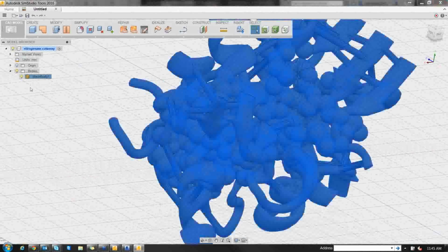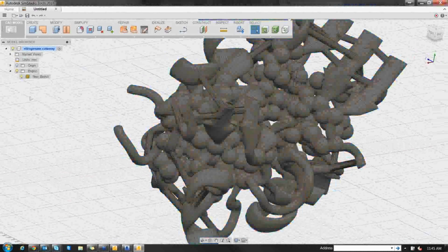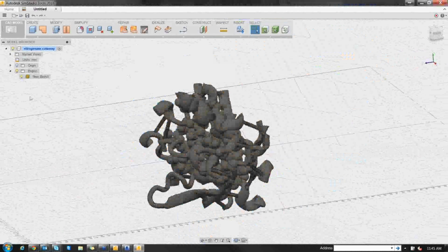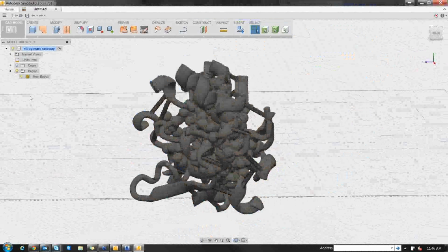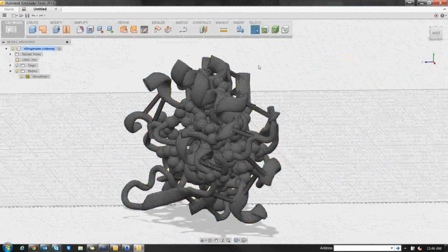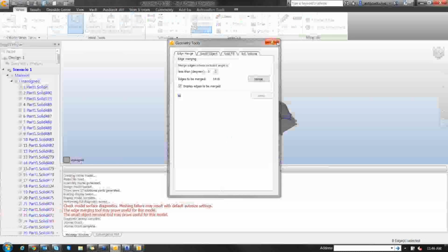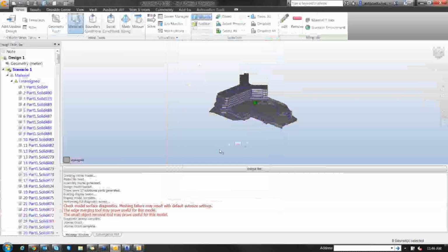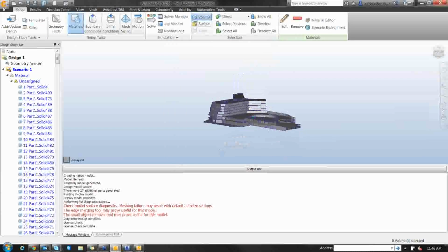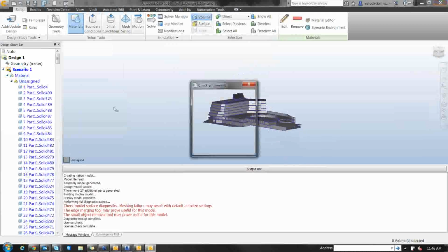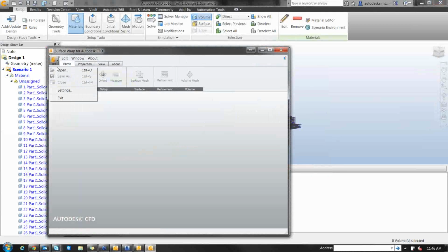It just wouldn't be brought in. But you could take that into surface wrapping, the surface wrap application, and it will put a surface mesh around it, and you could use it that way. That's the only way to work with STL geometry, unless you convert it into solid geometry today. More to come on that for future releases, I can tell you that.